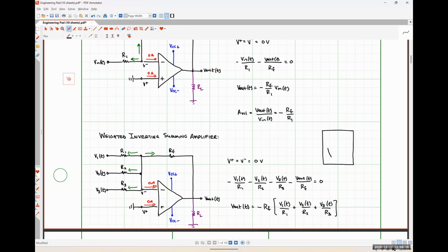And then it's got a little deal here that tells me where to put my left foot, and a little deal here that tells me where to put my right foot. Underneath here, there's what's called a load cell. So there's one at the front of your foot, one at the back of your foot, another one here, and another one here. Each one of these load cells generates a small voltage, on the order of millivolts, an amount of voltage that depends on the amount of weight that each one of those cells sees.